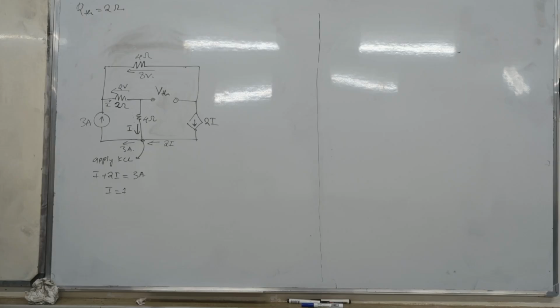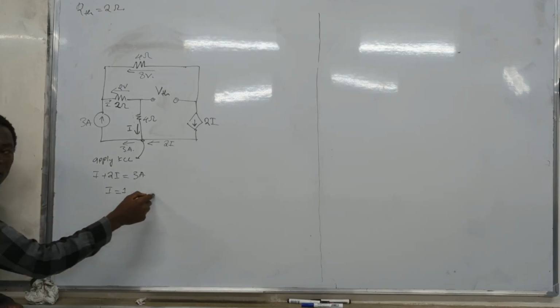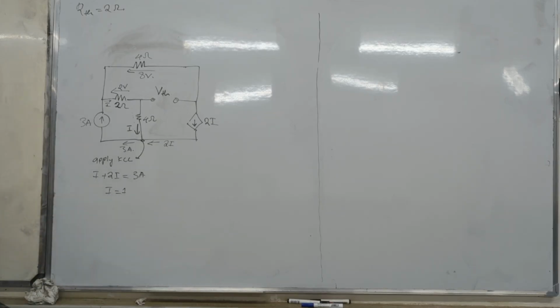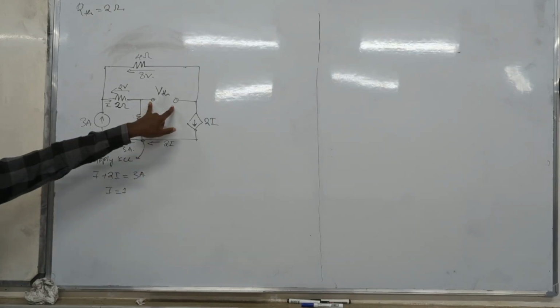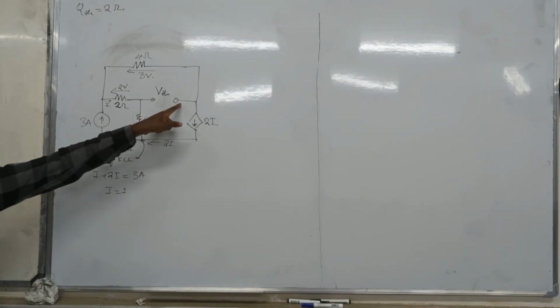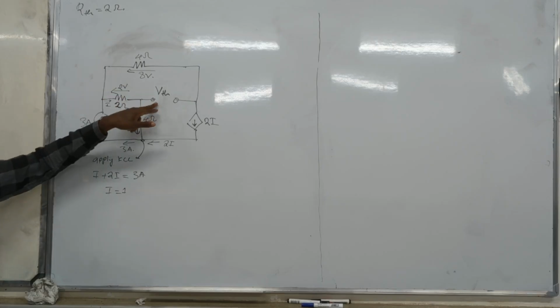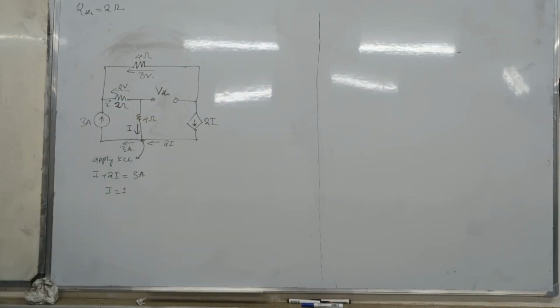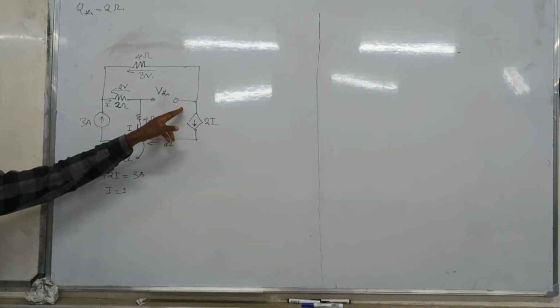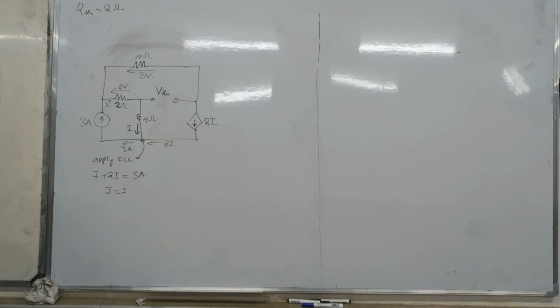You are walking along a loop. So that's how we can get VTH. We assume it's 0 volts. You can assume any value. Because if I assume, let's say it's 5 volts, I walk, find the voltage, then find the difference. But if I assume this as 0, there's no need to find the difference because it will be whatever value minus 0, which is just that value. It's up to you.